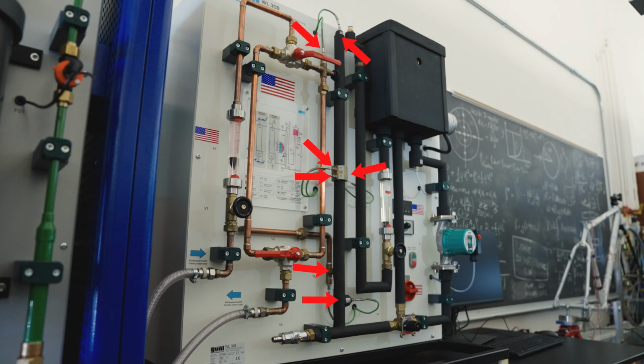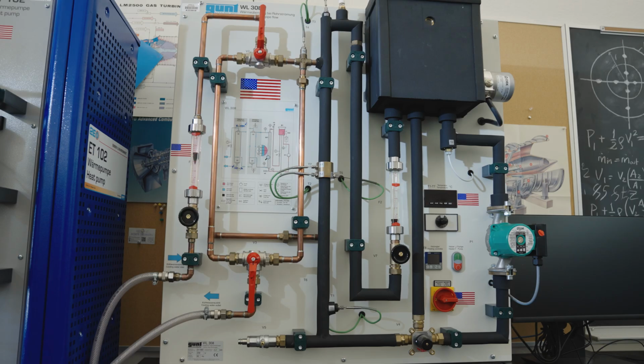7 temperature sensors are located throughout the device. These sensors provide the inlet, center, and outlet temperatures of the hot and cold water and the outside temperature of the inner tube. Refer to the lecture slides and device manual to see the specific location measured by each temperature sensor. The display shows the reading of a chosen temperature sensor. The knob below the display allows the user to choose the temperature sensor displayed.